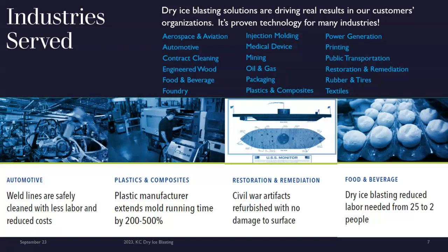There's less labor. One or two people ice blasting can replace 15 to 20. It does reduce costs over large cleaning applications like food and beverage and different molds, plastic molds. It does a very good job of cleaning every nook and cranny and pulley systems, machinery that rotates. There's no damage to the surface. It can be used for restoration in fire, floods. It's a very good all-around cleaner for anything that needs to be restored.